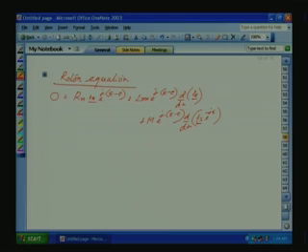Okay. So, this is with respect to rotor axis, this is also with respect to rotor axis. So, multiplying by e raised to j (epsilon minus rho) will go to the alpha beta axis, and then again from minus rho it will go to the dq axis. So, this dq rotor equation is defined with respect to the dq axis.